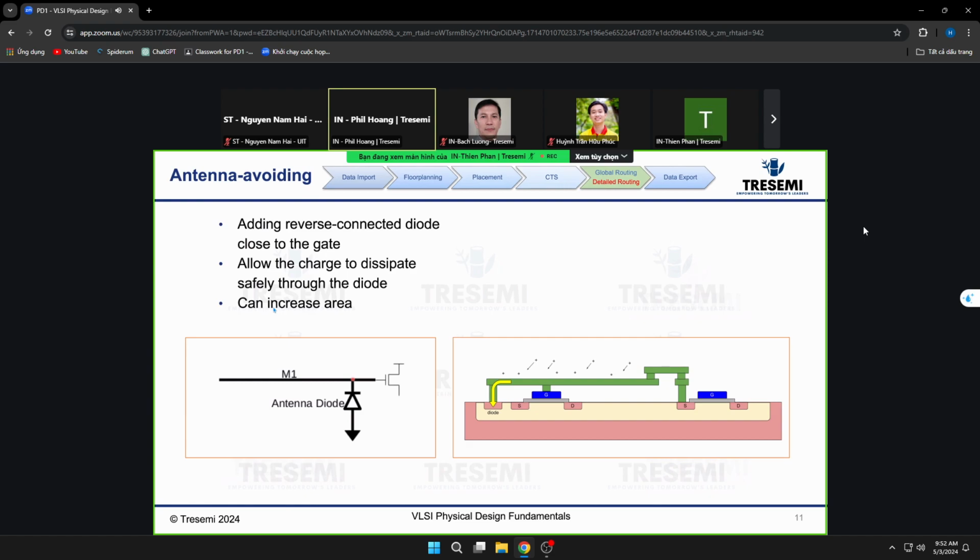Sure. Just keep in mind that this is only for black boxes where you have no choice. Usually you don't insert diodes everywhere, because of the cost. But for analog blocks, inserting a diode at the input of a digital gate is really not a big deal.